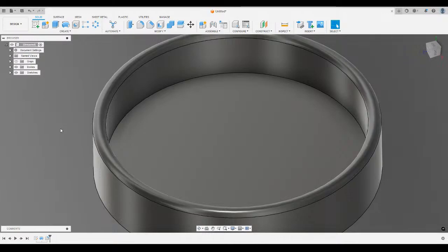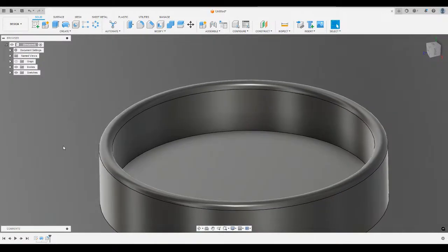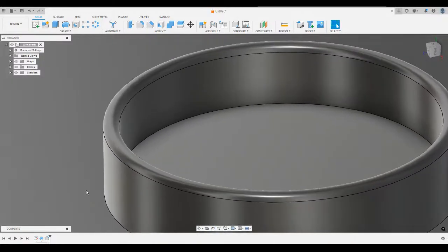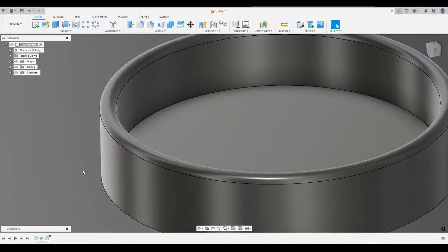Okay, this is going to be a little bit more advanced, but why would you, aside from aesthetics, want to round over your edges? In part design, model design, part creation, the engineering behind why a part is designed a certain way, sharp corners create stress concentration zones.